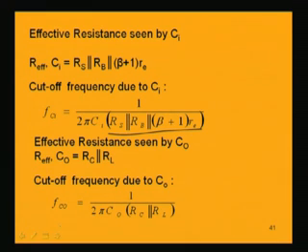So, now we have the two cutoff frequencies. As earlier in the low frequency analysis we got three cutoff frequencies and took the largest of the three, here we will be taking the lowest among the two, because if we have a number of cutoff frequencies, in the high frequency region we take the lowest value.